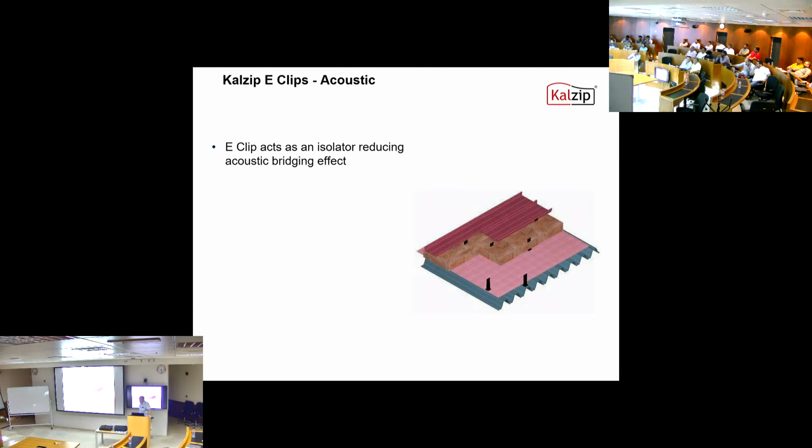Depending on what flexibility, we've done a test and we've got 52 dB. We've also done another test where we've put an underdrawn ceiling below the purlins and we've got 71 dB, so we've got a bit of flexibility. We have a specification for cinemas where it has an acoustic board in, 10 mil board and high quilt insulation, and that achieves about 49 dB, and it's a simple construction.